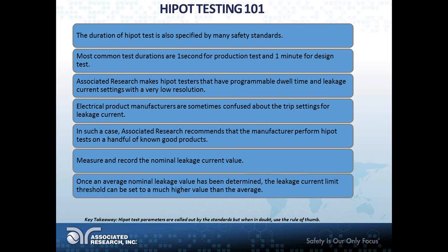So for a 1 second test or any short Hipot test, the Hipot's output voltage must not be less than 100% and no more than 120% of the specified test voltage. That's just another additional point that I wanted to pass on to you guys.